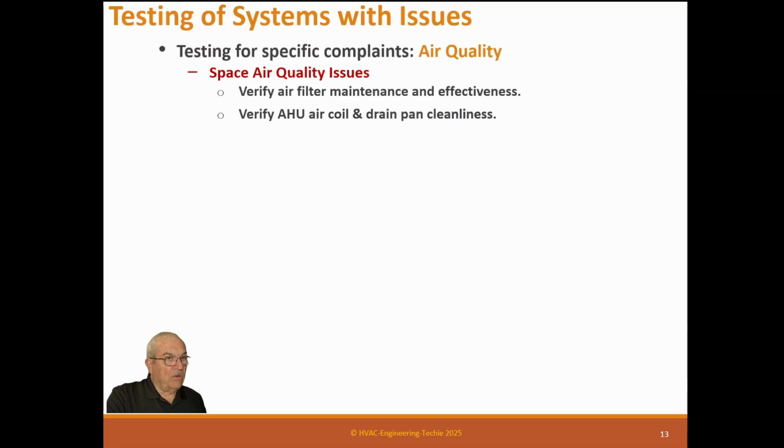Verify air handler and air coil drain or pan are clean. Verify that no chemicals are stored in the air handler plenum area. You're not supposed to store anything in an air handler area, but unfortunately people don't know. So a lot of times the janitor crews will store their stuff in an air handler room. They say, look, man, it's got lots of space. They don't realize it's part of the return air plenum.